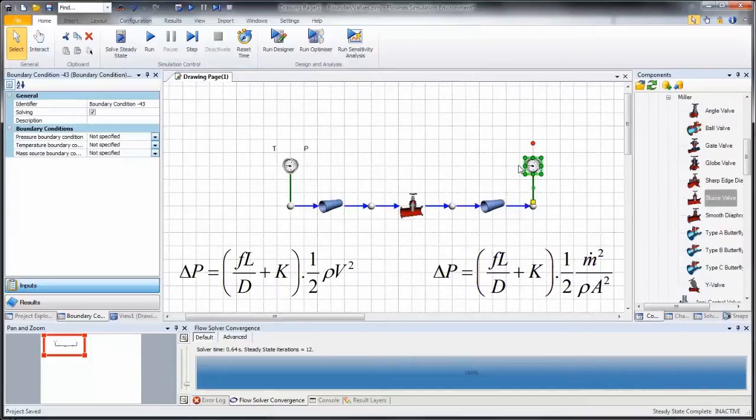So with the specified geometry, I can calculate the pressure difference if I know the mass flow, or calculate the mass flow if I know the pressure difference. So I can specify either of the two to calculate the other. But specifying both will be overspecification, and for this reason, Flownex hides the alternative input as soon as I selected the one I want to use.